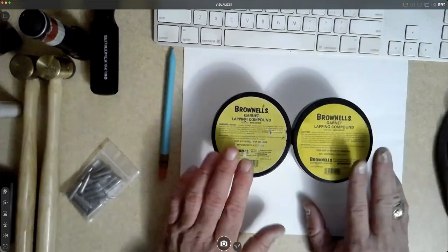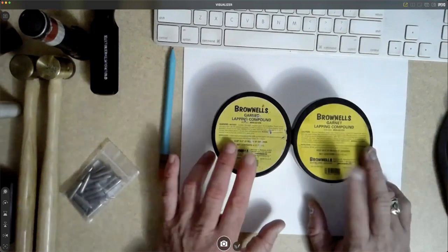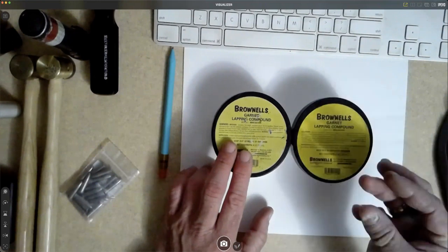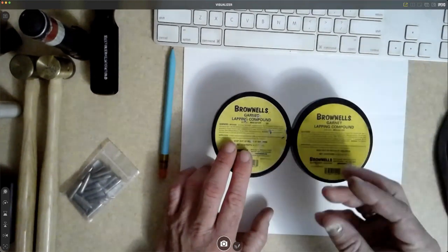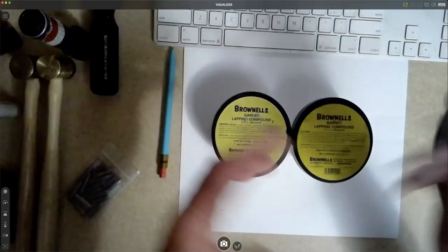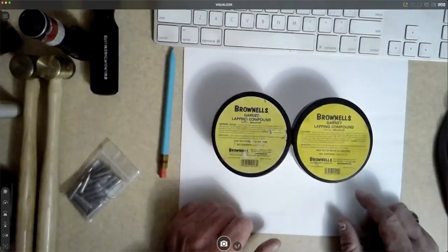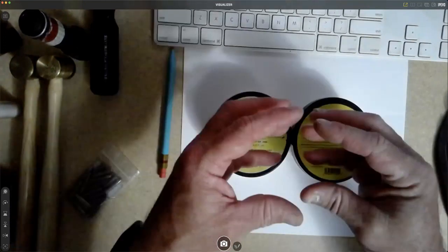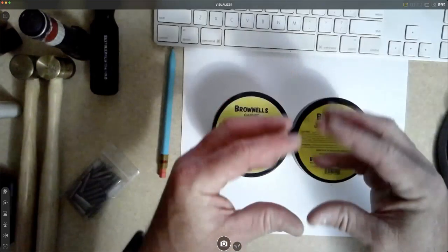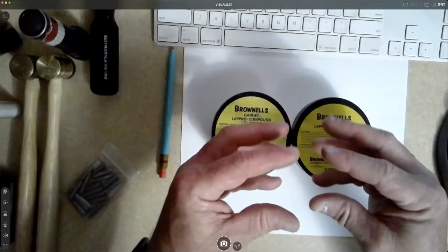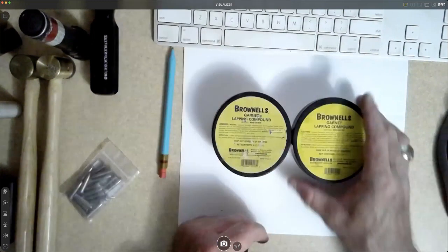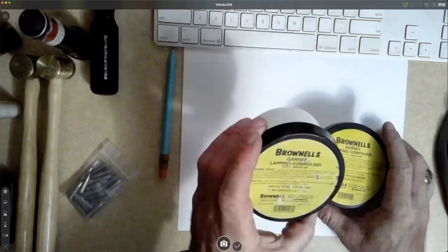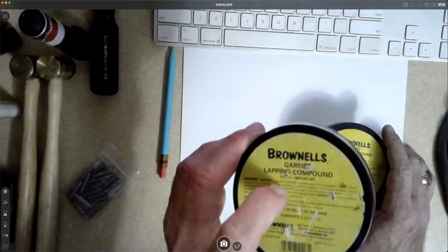No. Now the other thing I'll use with this is the cotton polishing wheel for a Dremel, or whatever your tool happens to be. I'll take that and run it on a piece of sandpaper to make it whatever diameter I need. I want it slightly oversized. This is 1,000 grit, and this one is 600 grit, so I would start with this one.